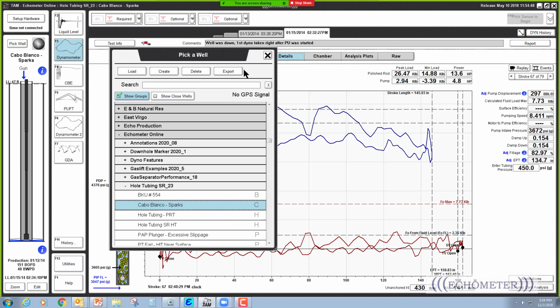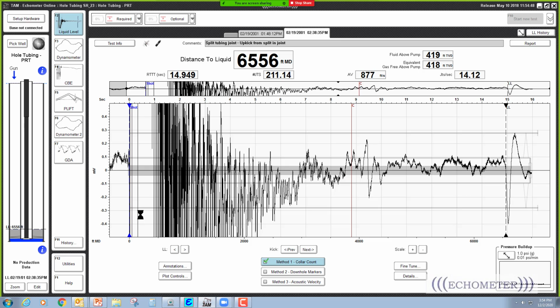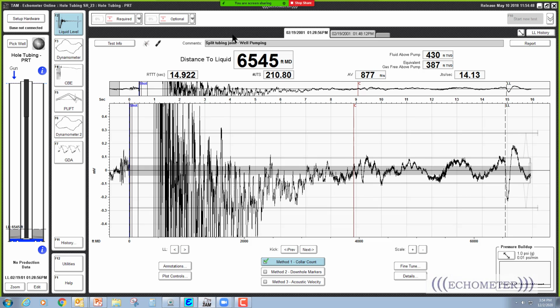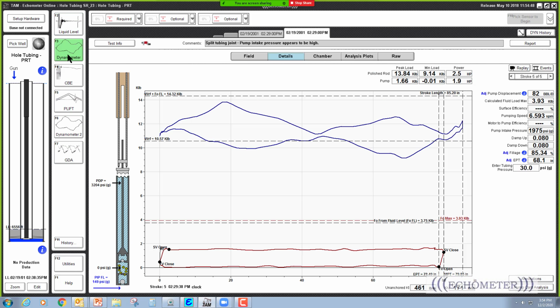Yeah. Okay, so this is the hole in the tubing a long time ago, before I realized that you could shoot down the tubing. The operator said no production at surface, and the pump card is full. The pump cards are full, and it's sitting on 0 because the polished rod transducer is used to acquire the data, and all of the pump cards acquired with the PRT sit on the 0 load line, whether they should or not.